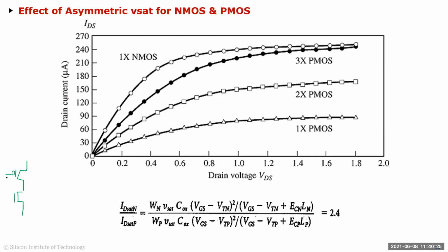So in the case of an inverter, for example, when Santanu was showing you the delays, you see that you had an effective resistance here, like RP, let's say, and this was some effective resistance RN, right? So you have the same cap. So you had a charging time, which we call tau P high to low.